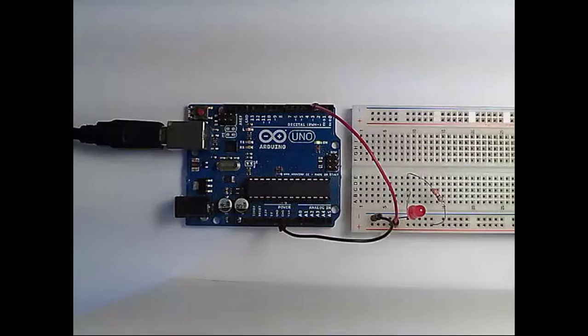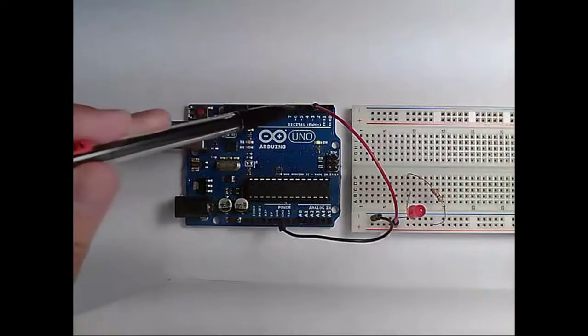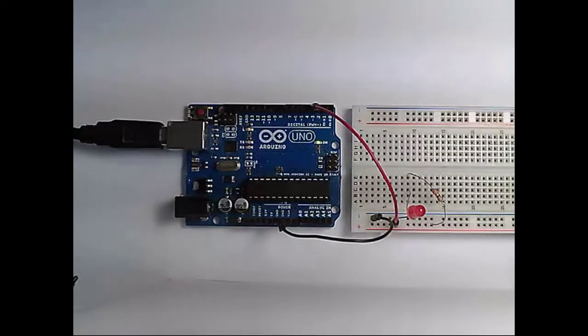Now, compile time errors can be relatively easy to catch. Often the Arduino IDE will actually highlight them for you, as we just saw. Runtime errors, however, can be more challenging to debug. If you look at my circuit more closely, you'll notice that the power being supplied to the LED here is connected to pin 3. However, in my code, I defined that as pin 4. So we need to address this runtime error.